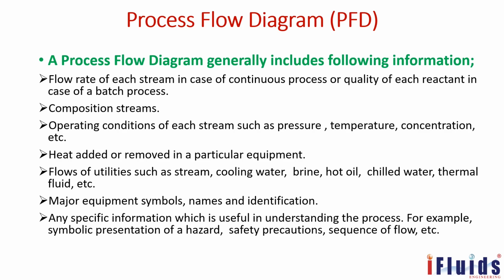Any specific information which is useful in understanding the process, for example, symbolic representation of hazard, safety precaution, sequence of flow, etc. Any specific information you want to put in the PFD, you can put it as a note, or otherwise put a star or a triangle. That information we can use.